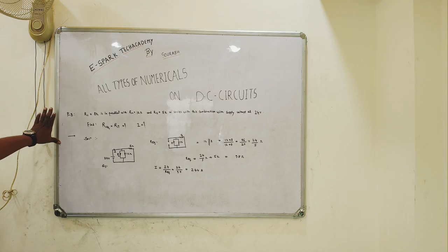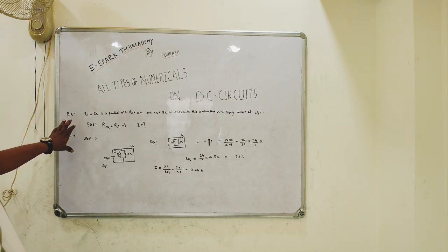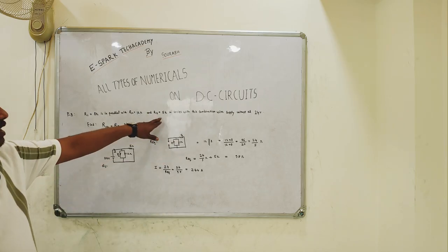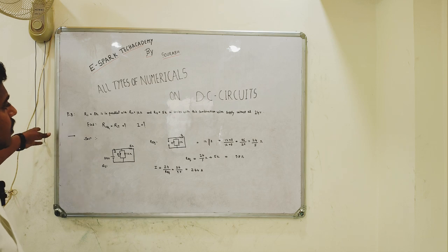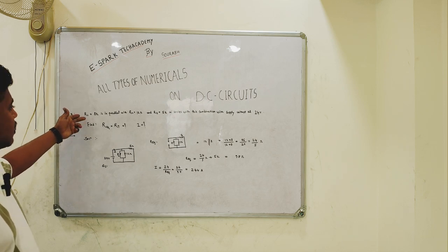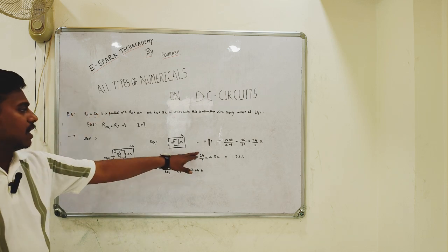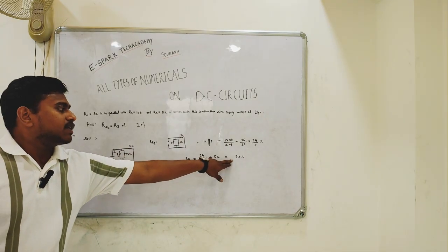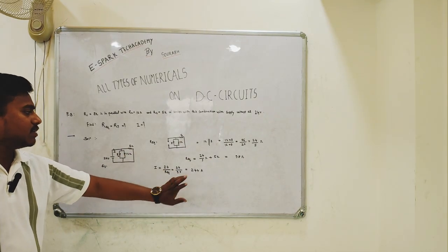As from the problem statement itself, they have already given that the R1 8 ohm is in parallel with 12 ohm and then it is in series with R3. You can also calculate in the same way. The 12 and 8 are in parallel, then in series with 5 you will get the R equivalent and then you will be getting this.